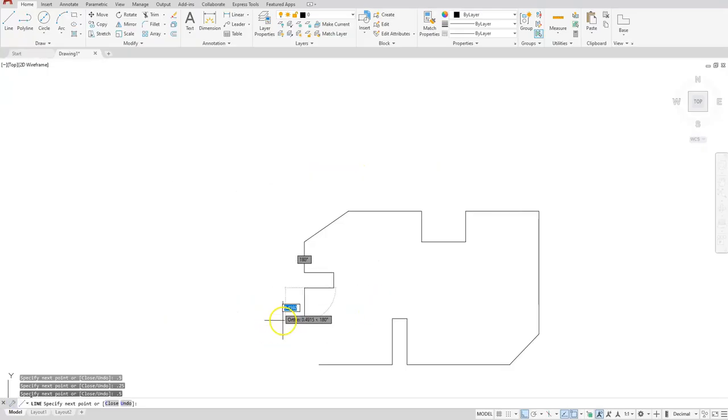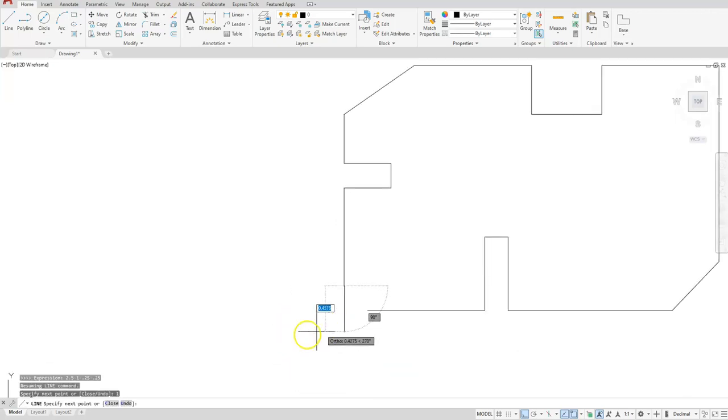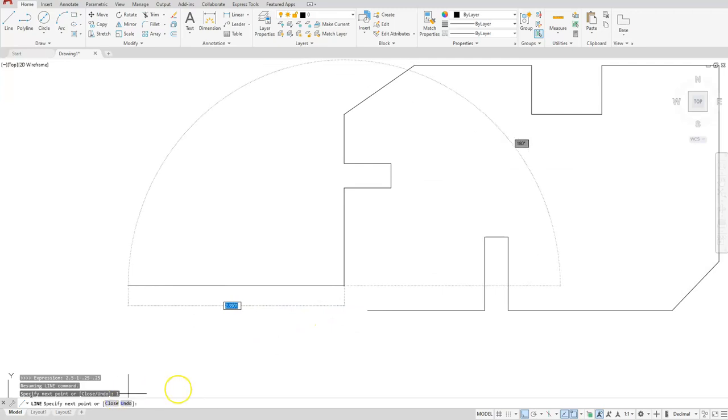Okay, so back here in AutoCAD, let's go and give us our preview direction. So we want to make sure that it's pointing down. I'll type in the calculator, so apostrophe CAL, enter. And then my expression will be 2.5 minus 1 minus my 0.25 minus another 0.25 here at the bottom. Enter. And you're going to see that your line should complete, and it calculated that distance of 1 for us.